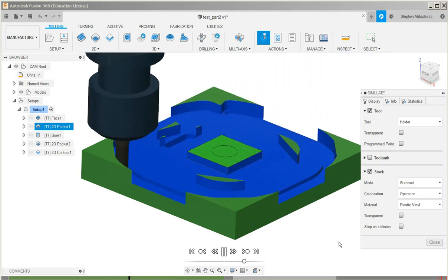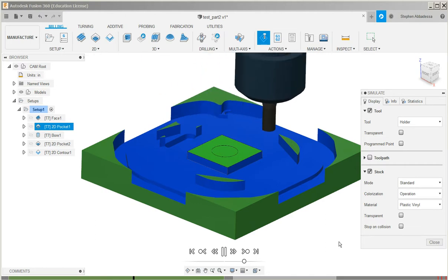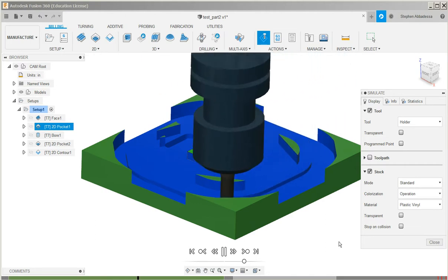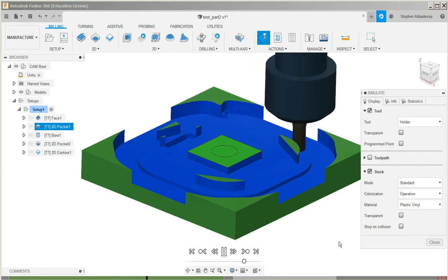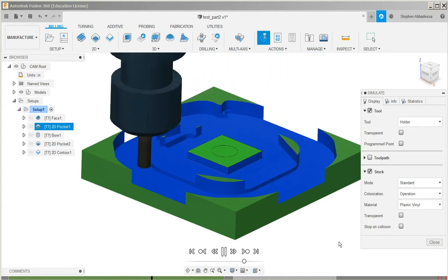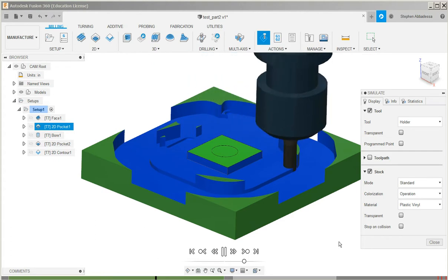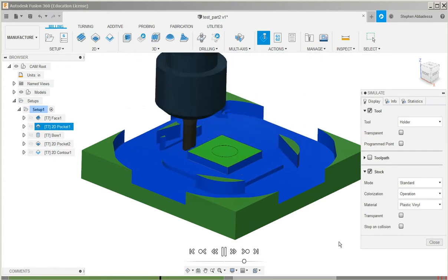And go down another cut. Again, you do not want to take off all the material at one time. Do nice gentle cuts, and that will give you a much better surface finish, and it will be much more gentle on the cutting tool.